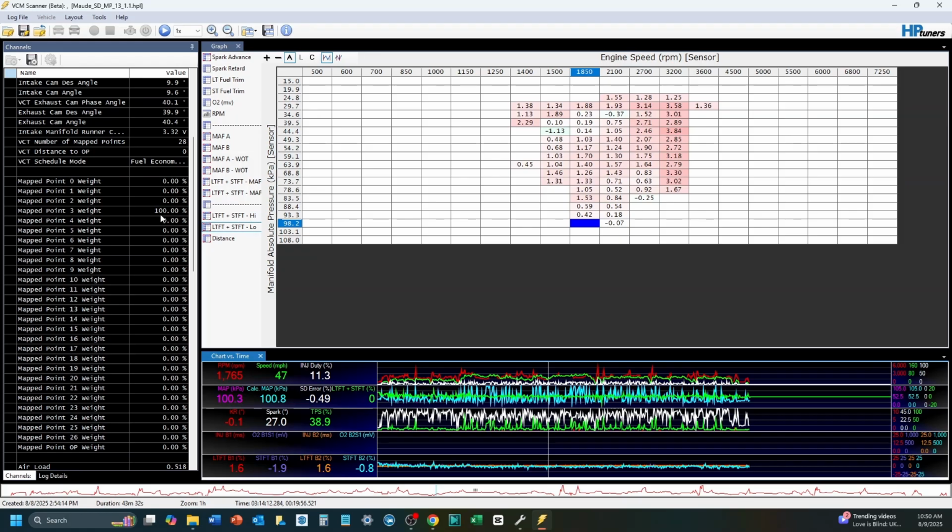The other thing I was going to mention, while you're taking your logs, it's very important with this process that we get accurate data and enough data, and that it's across all of the different situations that the vehicle's going to be in. So like with any speed density log, when you're doing math, you can just do a couple of rips down the road, 10 minutes, go and adjust, you can bang it out in an afternoon. It's no big deal. With speed density, because you have to hit all these various pockets, it's going to have to be a pretty long drive, right? And I've actually gotten this down to, for the most part, a 3-step process.